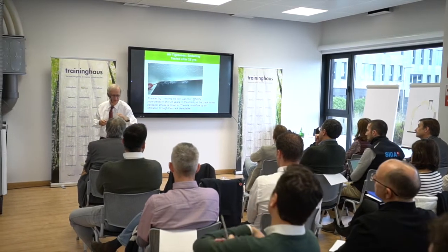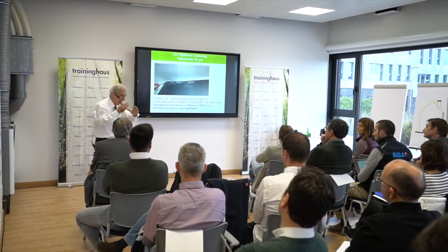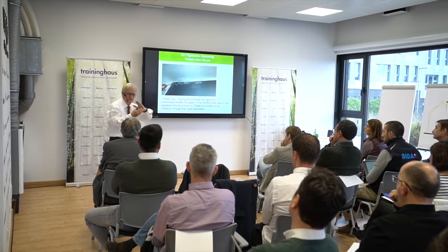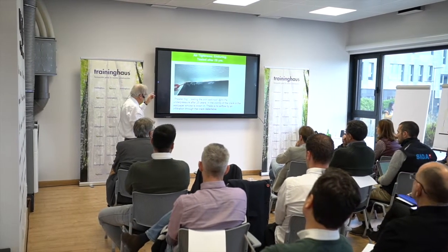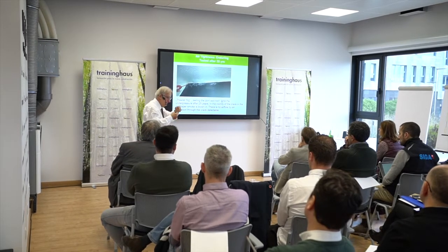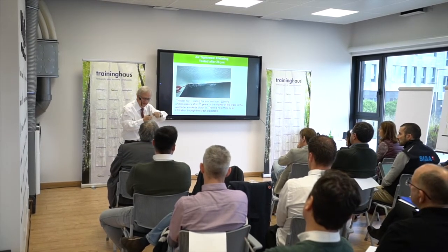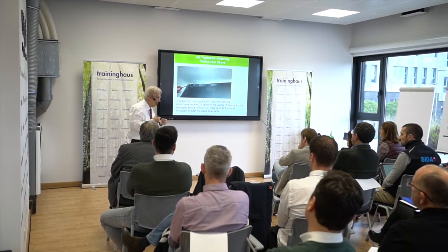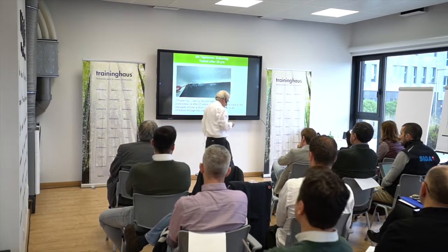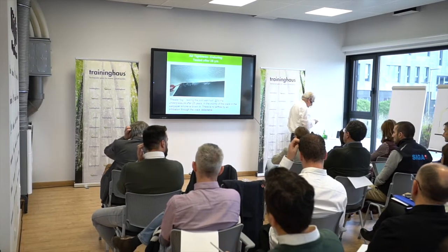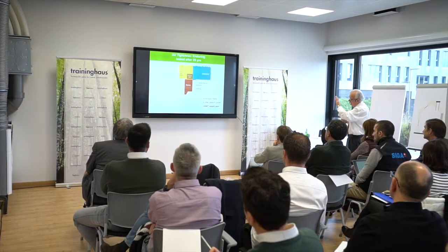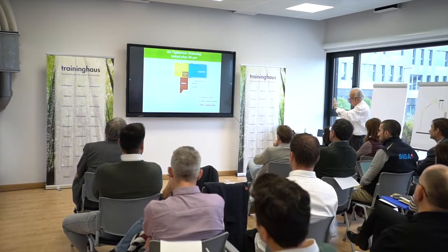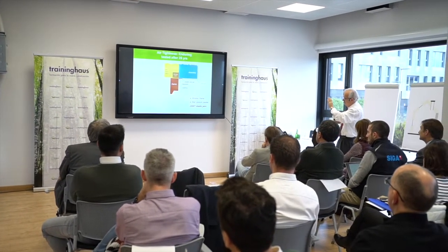It will never work because there's always movement between the roof and the wall. You cannot avoid that movement. So there has to be a layer which is capable of staying airtight with this movement. That's one solution I showed, another one Paul has shown. So yes, we have solutions to that. This also gives you some ideas how such types of problems can be solved.